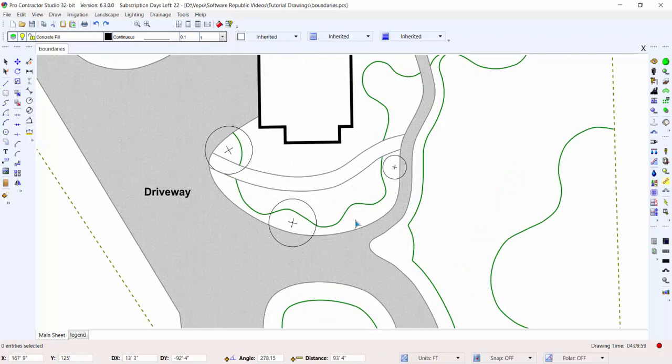When creating a boundary around a complicated area with lots of changes in direction or areas within areas, use the selection method to create the boundary. The command performs faster when the boundary entities are selected because it does not have to search for them. It can simply check to make sure they intersect and then create a boundary based on the perimeter.